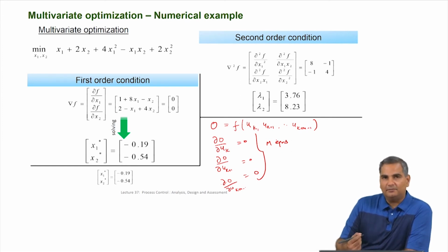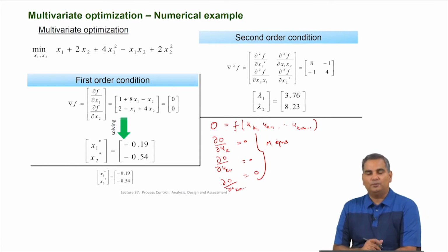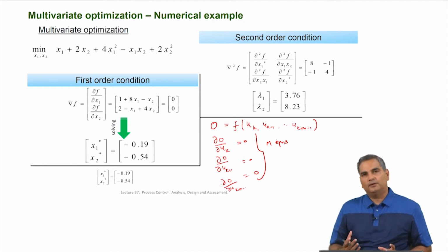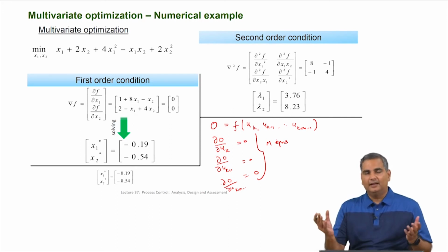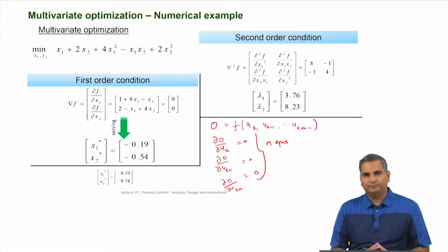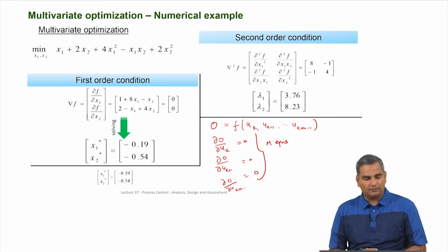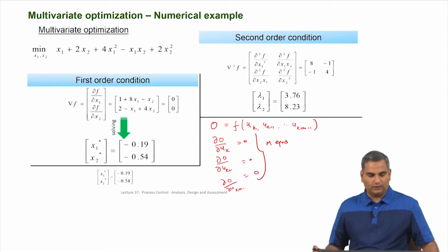It will actually minimize my objective function, which means that I am going to be able to follow the set point trajectory as closely as the system would allow me to, while not expending very high control effort. So, I have the two terms, and based on the application I can emphasize one term, de-emphasize the other term, and so on. That is how all of this works together.